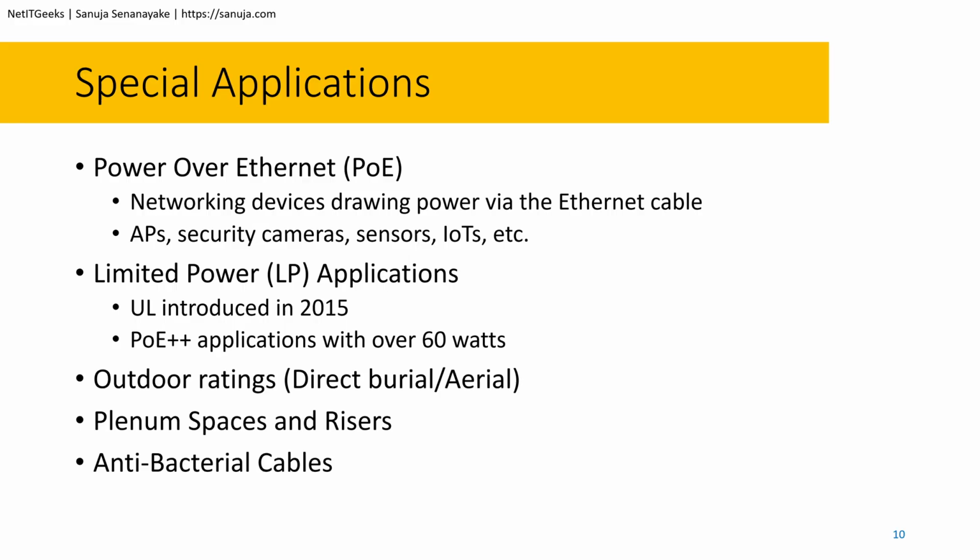What may be a factor that you may want to look into is the manufacturing quality of your cable with PoE. If you are putting cables in industrial applications where the PoE power draw is much higher, and you are putting cables outside the building where they are exposed to the elements with power over Ethernet, keep that in mind. You need to buy good quality cables, especially with power over Ethernet, when putting them outside in industrial applications as opposed to home or inside building applications.